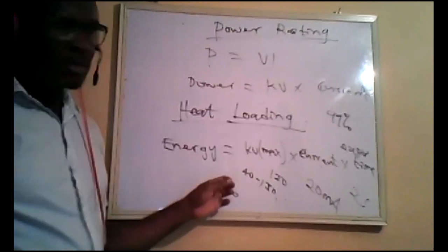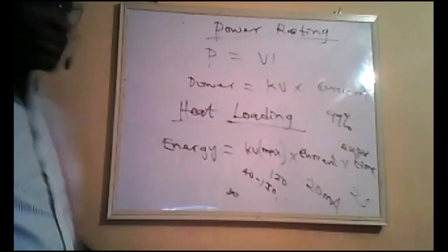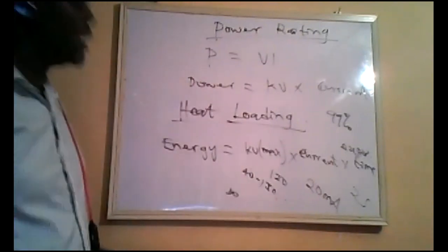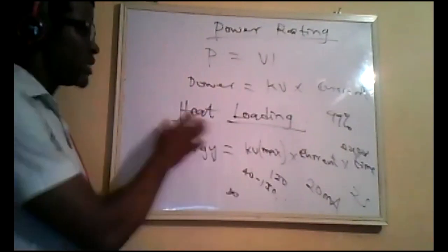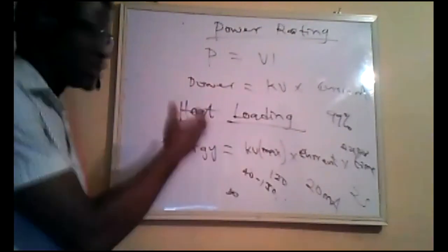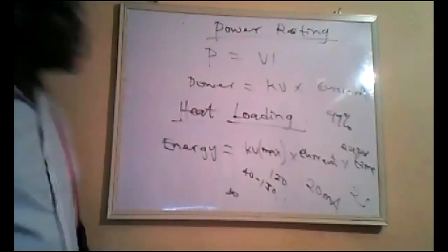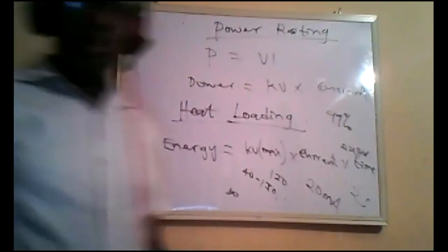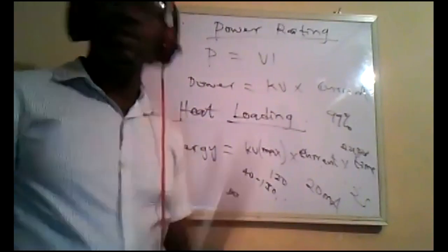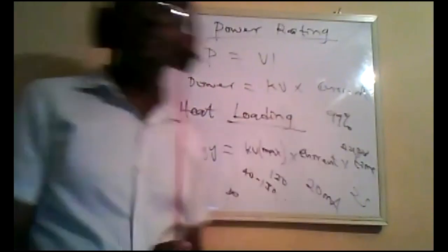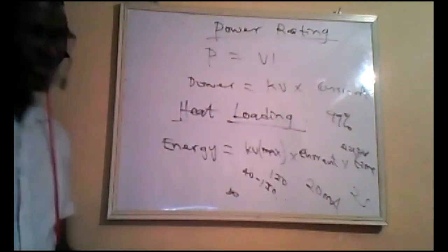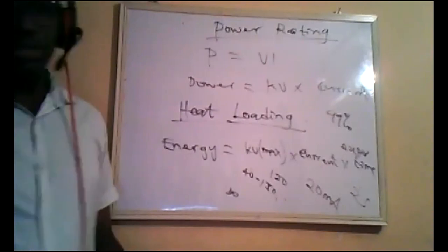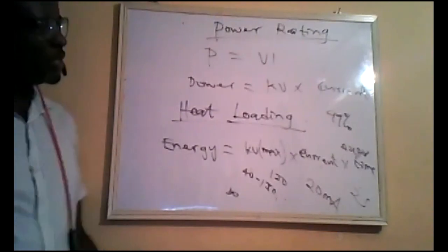that machine. So this heat loading helps us to quantify the amount of energy at every point in time, at every exposure. Because as the machine is continually heated, cooling also takes place. So the rate of cooling and the rate of heat production should be about the same. If not, you're going to heat up the machine and it might damage the tube.